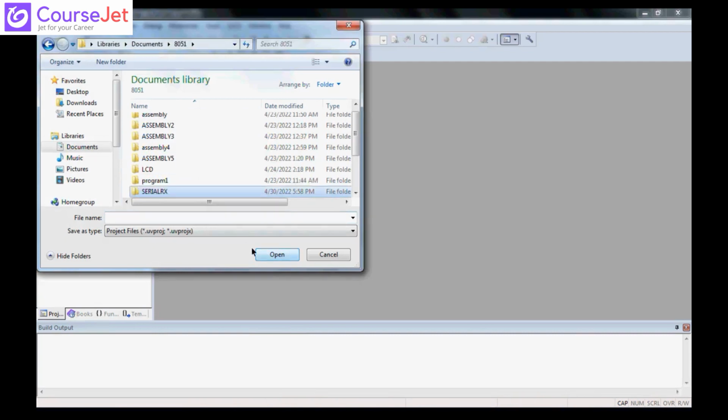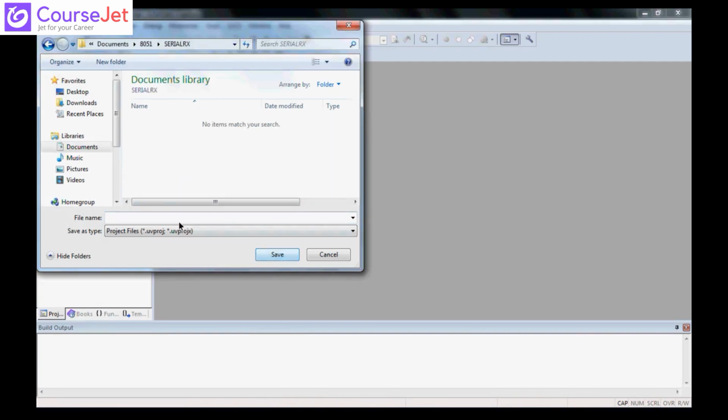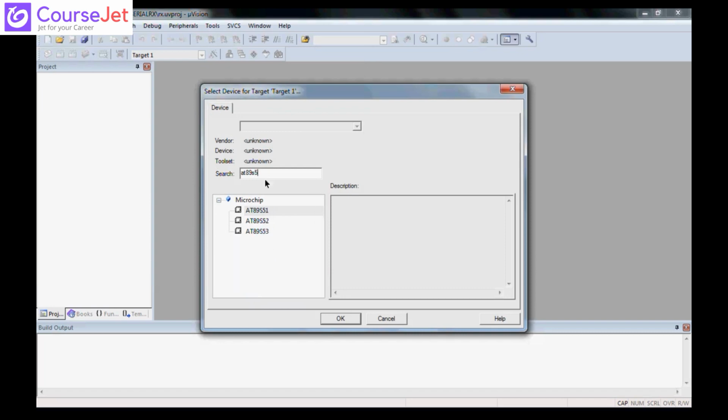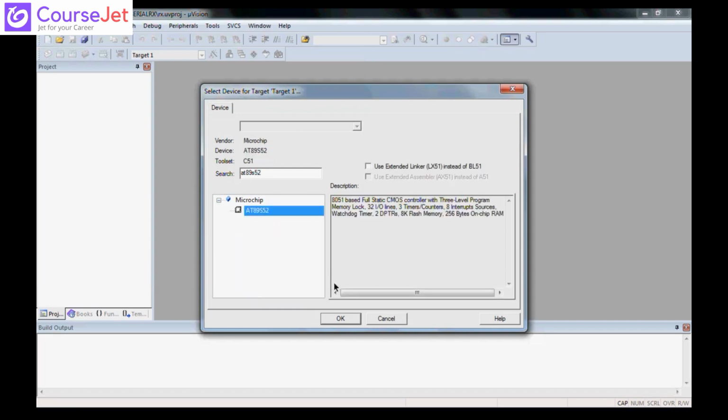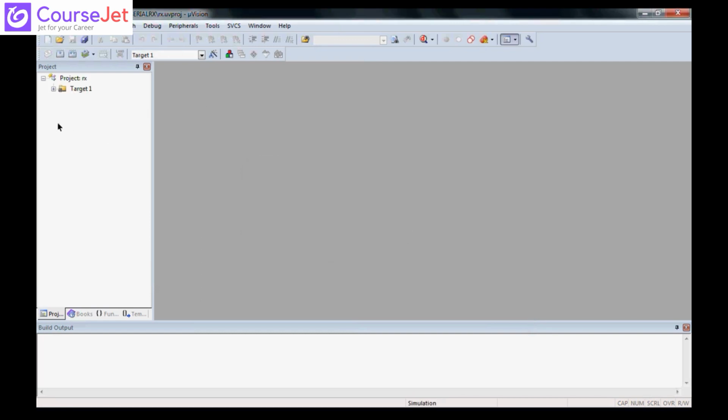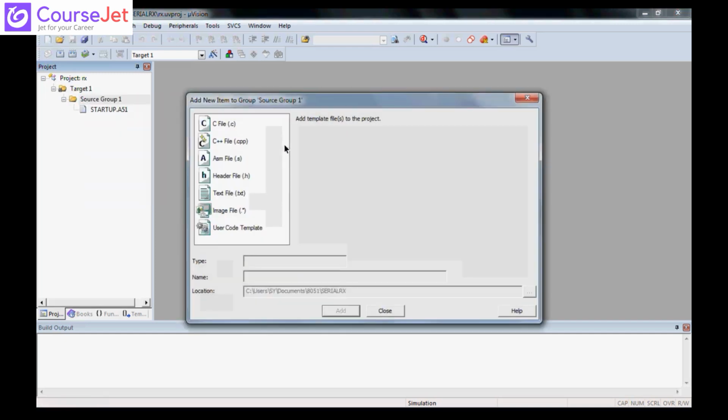RX. Now we are writing one program for RX, and this we will not be able to execute in your 8051, I mean Keil software. Why? Because from external, how we are going to send it. So we will write our program, but execute it on Proteus only.